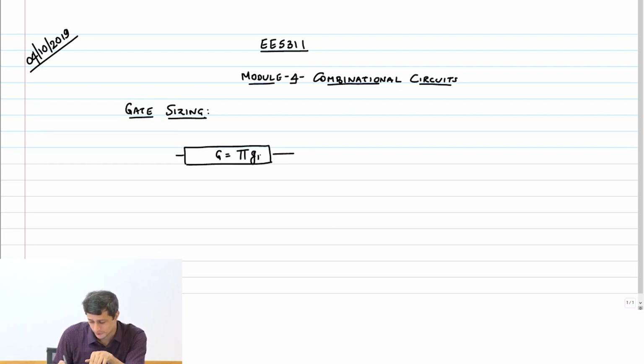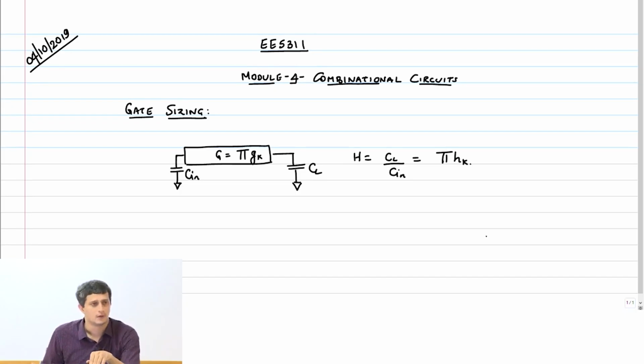the individual logical efforts, right? And if the load capacitance is some value CL, and if the input gate presented a capacitance of Cin, then the path electrical effort was CL by Cin. And this again, by the way, is just the product of the stage electrical efforts. So the path effort F is just G into H,